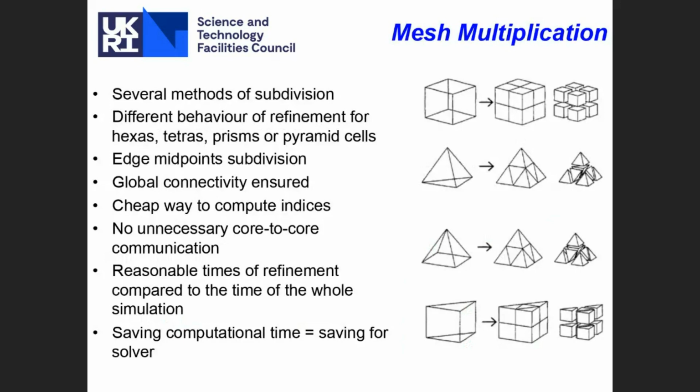The other technique to generate massive meshes is to start from meshes that we can manage. Meshes we can manage can go up to, let's say, 25 to 40 million, and really up to 100 million with a massive stretch. Then the idea is to use a technique called mesh multiplication. You refine globally all the cells of the mesh.